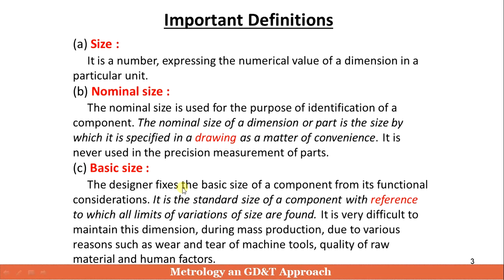Then we have a basic size. It's usually the size with some sort of reference. So over here we have a zero line as a reference. From that position, if you mention any dimensional and numerical value, it will be called a basic size.